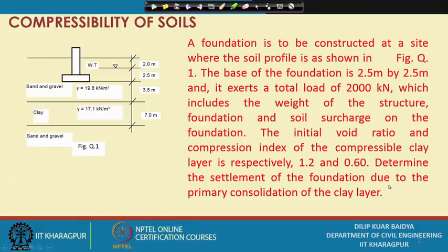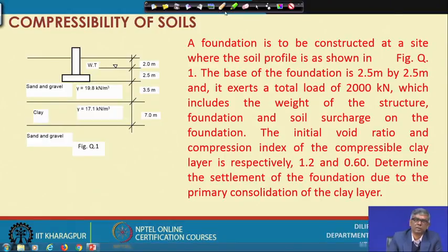You can see, though we have not learned geotechnical engineering or foundation engineering, this is something one has to understand: at the end of every column there will be an enlarged base, which is nothing but a footing. Why do we enlarge this? To reduce the pressure. This column carries some load, and if I directly put it on the soil, the soil will not be able to bear that much pressure. To reduce the pressure, we enlarge the base. This is the footing size, so the footing will be much bigger than the column size.